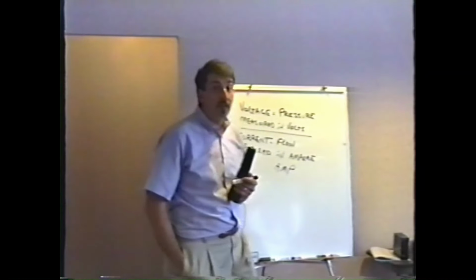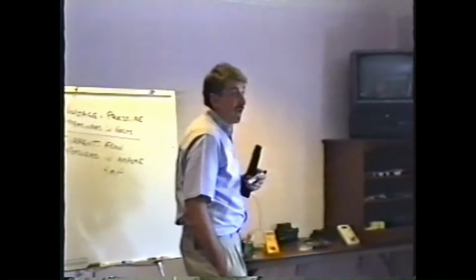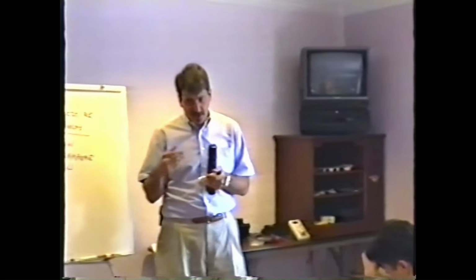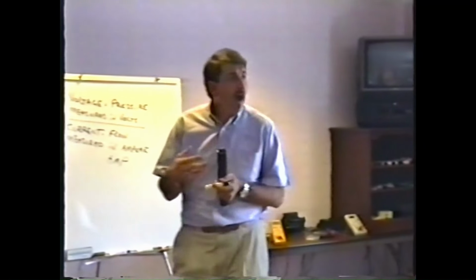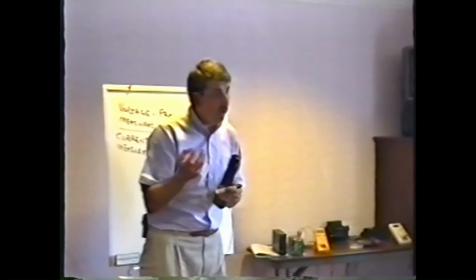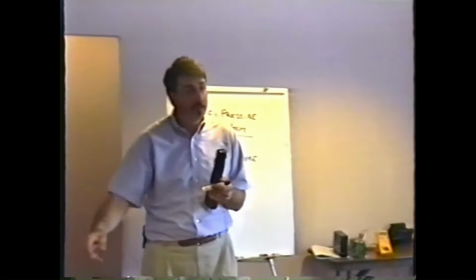In fact, the only time that I've ever measured electric current in a game is just out of curiosity, to see how much electric current a game draws from the wall receptacle, or how much a logic board might draw from a power supply. And by the way, your average video game only draws about 1.5 amps to 2 amps out of the AC power receptacle. This is especially important for those of you that work in arcades or setting up arcades.